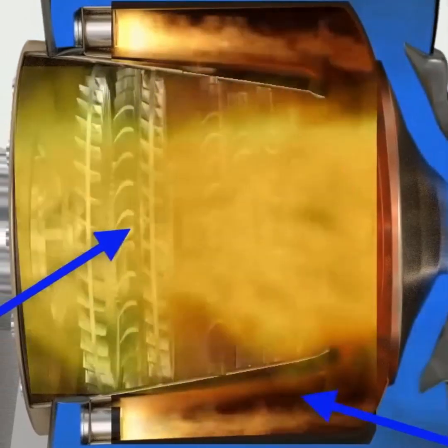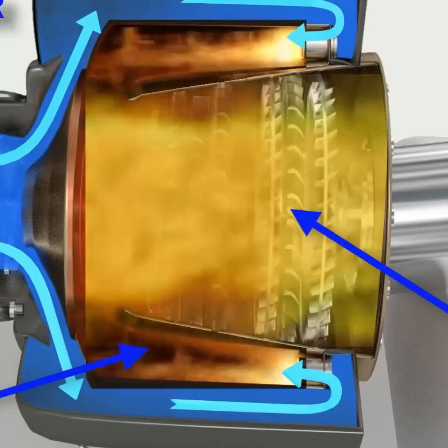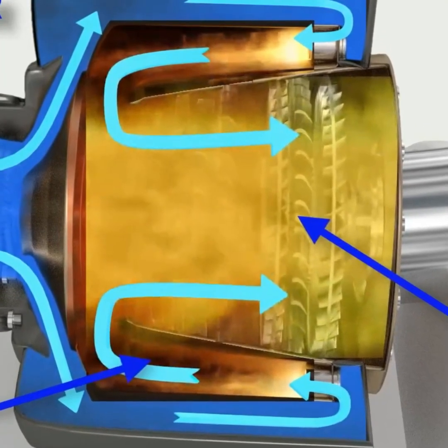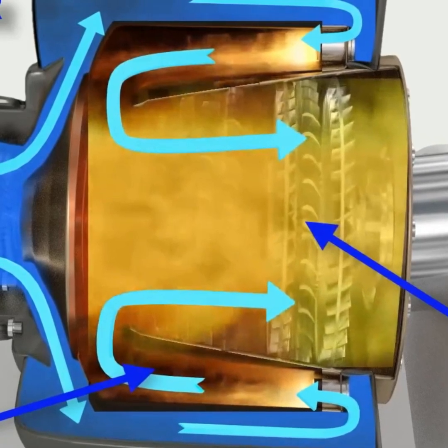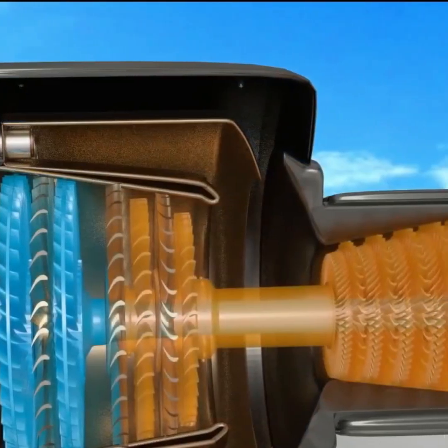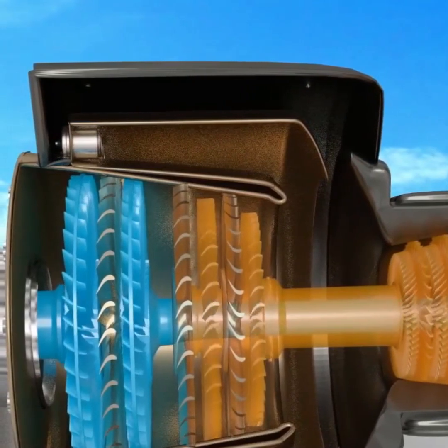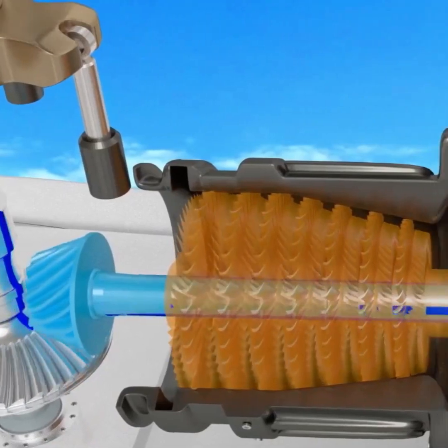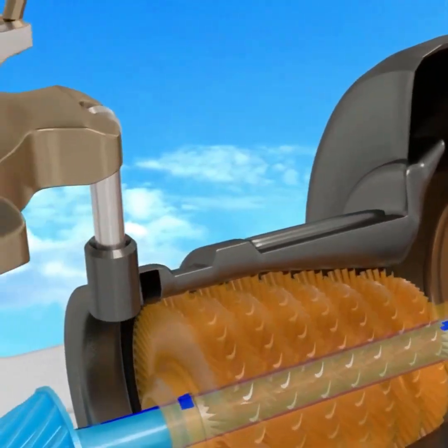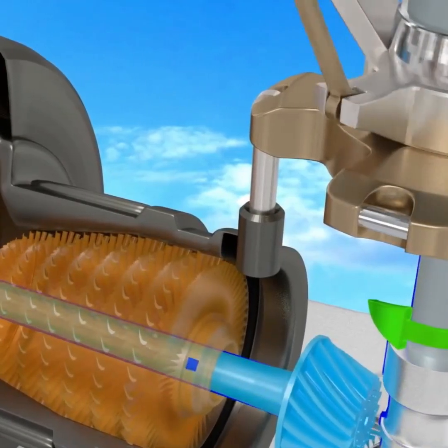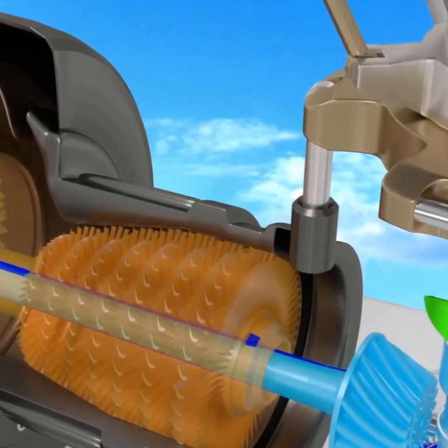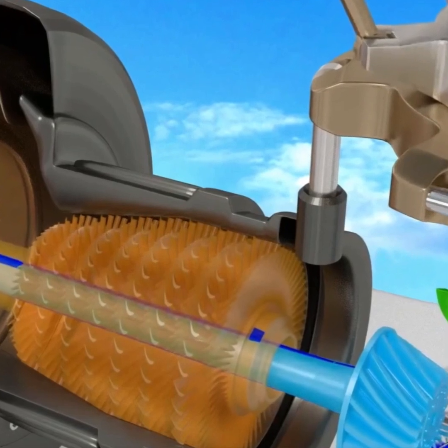The compressor draws air in and compresses it. Fuel is then burned in this pressurized and hot air. The hot air that exits the combustion chamber passes through a series of turbine blades, causing them to rotate. There are two sets of turbines. One set powers the compressor, and the other set drives the rotor shaft of the helicopter. While jet engines in aircraft generate thrust, the primary function of a helicopter's jet engine is to rotate the rotor shaft. The most challenging aspect of flying a helicopter is controlling it.